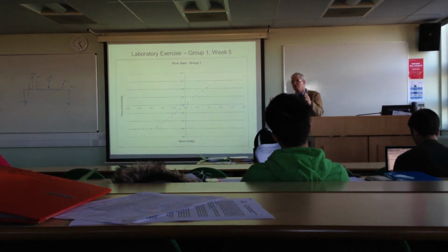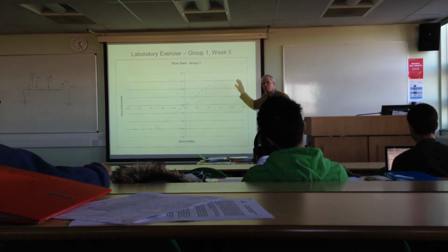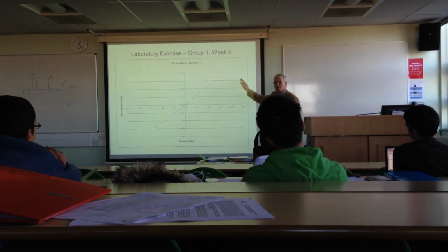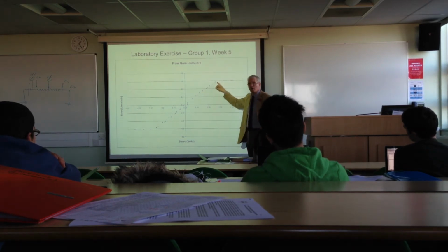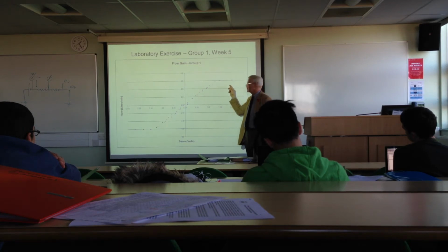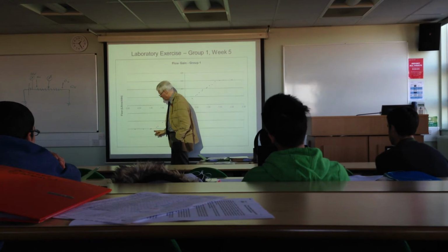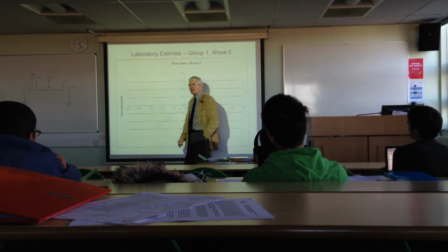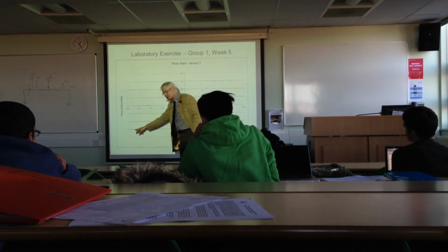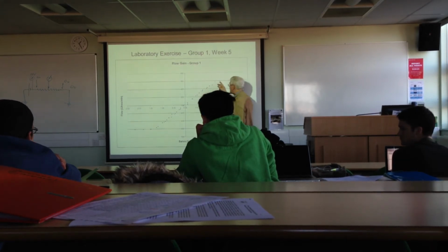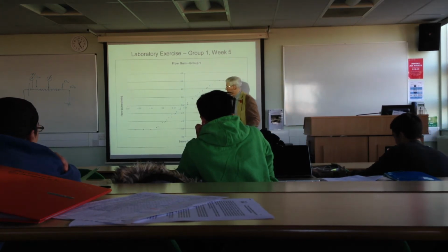And the two groups, effectively, one group started over here with the motor going at maximum velocity in one direction. And we gradually reduced the voltage, and nothing happened to the flow rate, because that was the pump at full chat. And then it went straight down here, and then we ran out of pump flow, and it went off round there. Then the other set of symbols started over here, and effectively did the reverse, and came back up there. There's the point that I'm a little bit suspicious of.